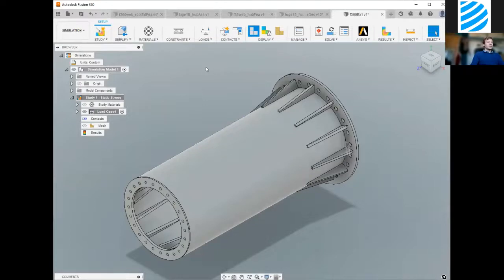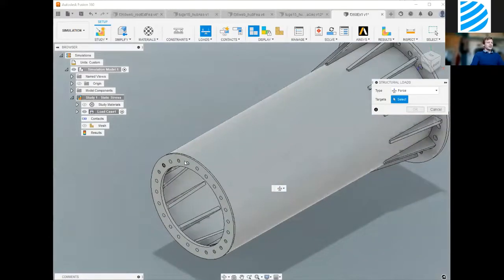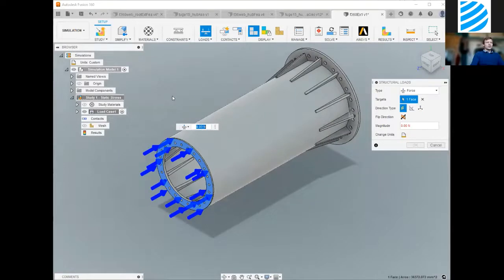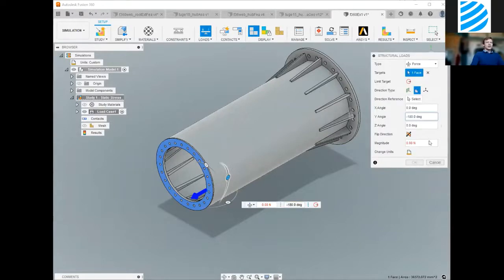And then we will add some loads. As I mentioned, the blade is bolted to this end, so here. And I'm going to apply 2 loads. One of them is the centrifugal load due to the rotation. So I'll just change the direction. So we're using this kind of angle option to define the direction of the load. And in this case, the load is 7 kilonewtons.